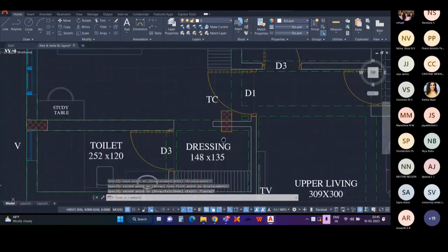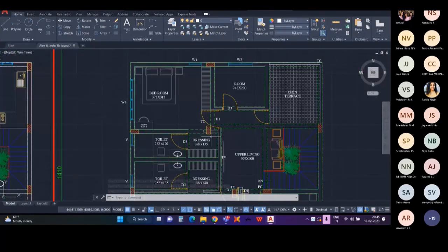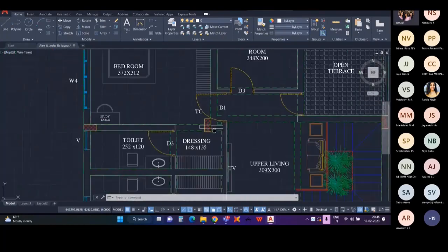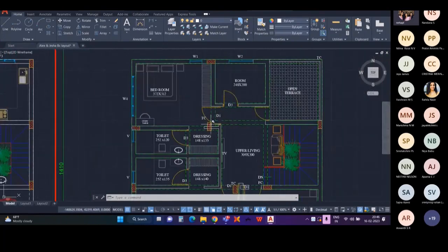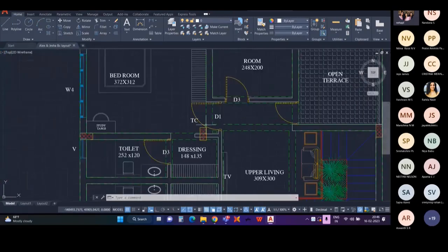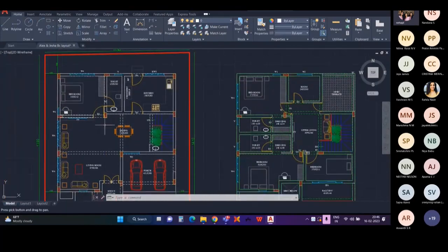Okay. When it comes to the first floor, this column was like this. It's a 10 thick wall, and this column, when it comes to the first floor, was like this. There is also a door which is coming here. This wall is also 10 thick, and this orientation is vertical. So the column will be going like this, which is not okay. So we cannot provide a continuous column like this.